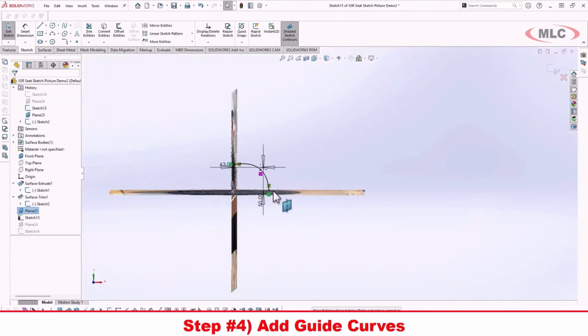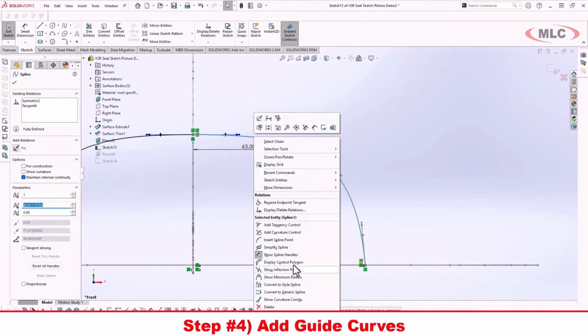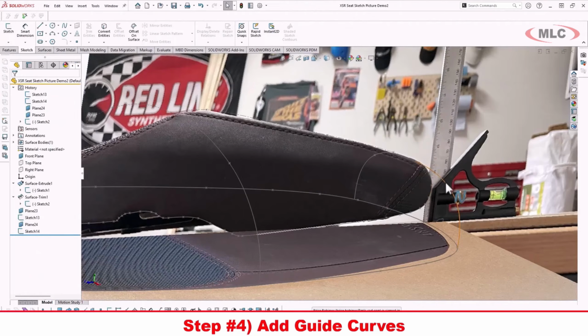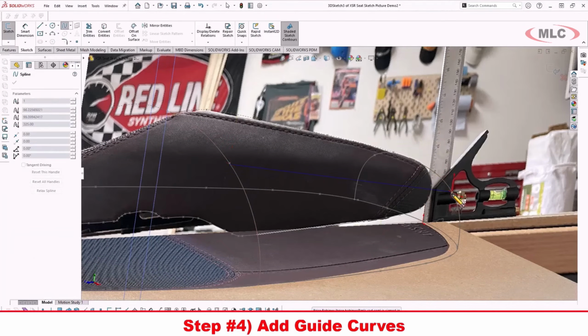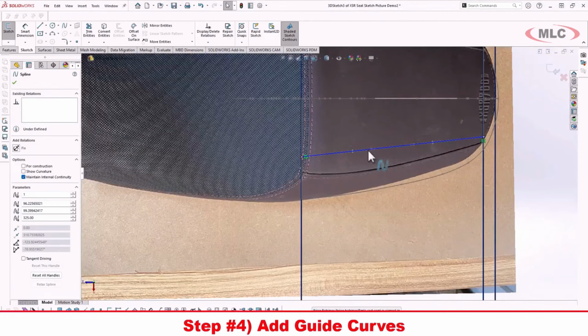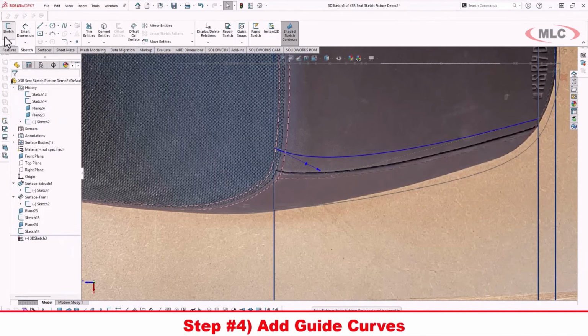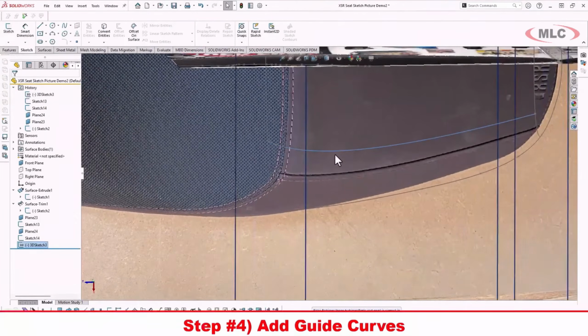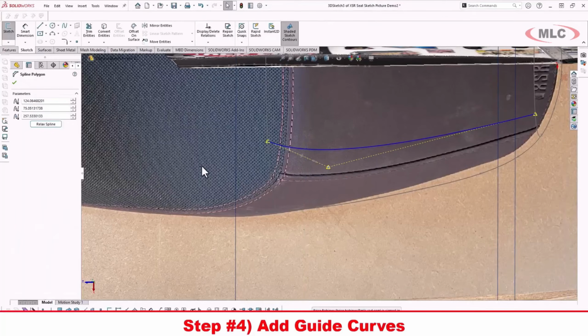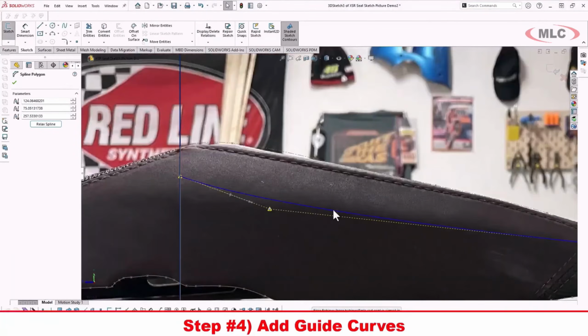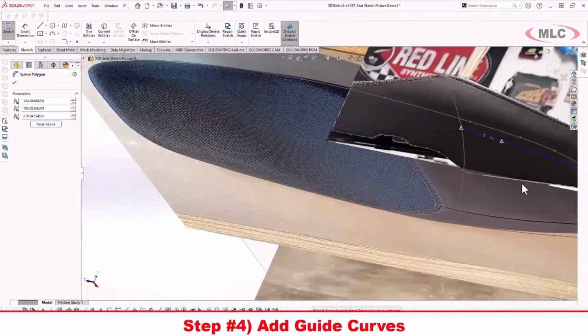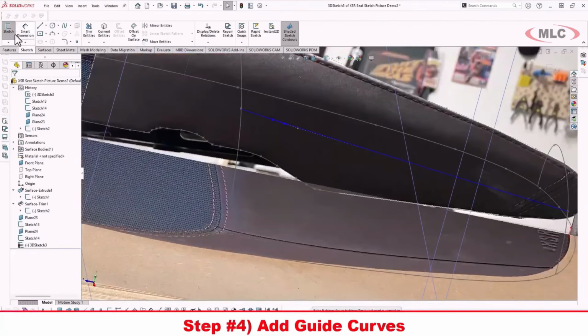And with those set up, I again wanted to split my surface up and use that main seam. So I did that by using a 3D sketch, which can be a really quick and easy approach for something like this. I drew out a spline and then flipped between my view orientations to manipulate that spline in the three different dimensions to roughly match the curve of the seam. The position isn't 100% accurate here because I used those measurements earlier, but the picture is still a really great reference to dial in the curve.